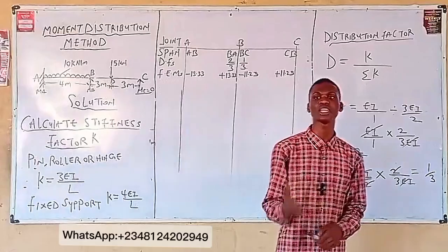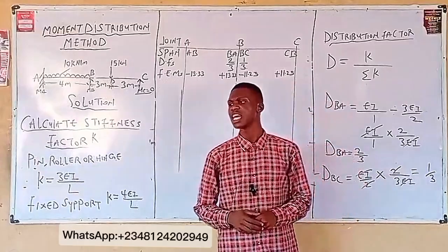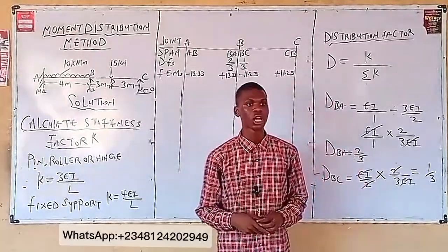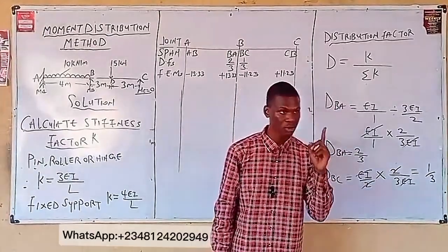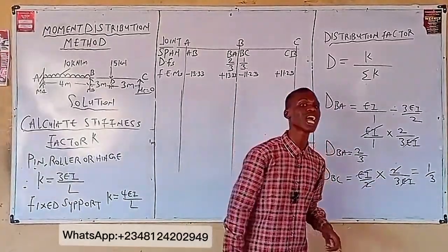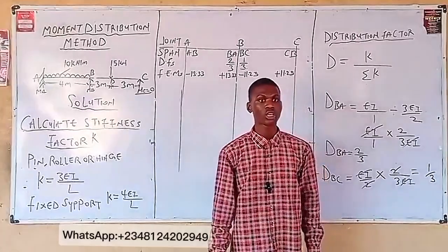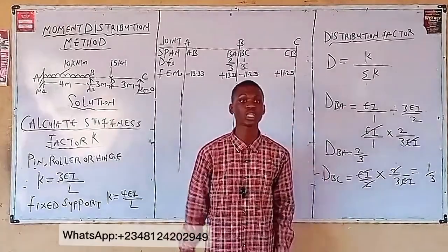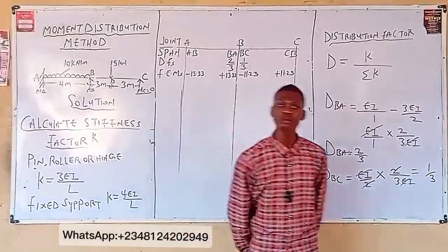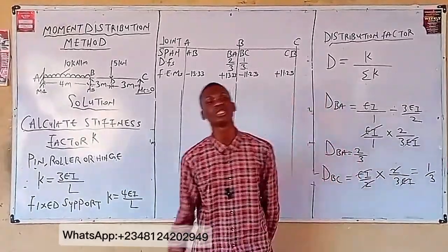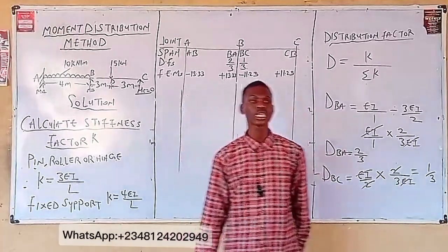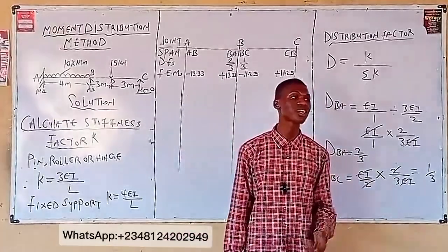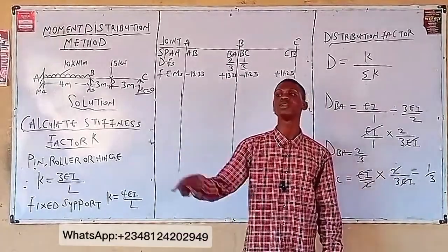You can relate this to shear force and bending moment. When we did shear force and bending moments, we said, given a simply supported beam, your bending moment starts with what? 0, and your bending moment ends with 0. The question is why? Why is my bending moment starting with 0, and why is it ending with 0?